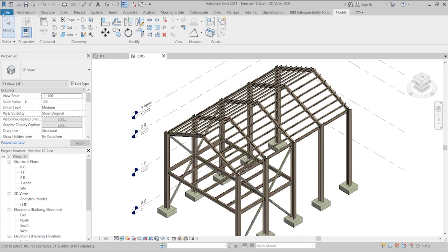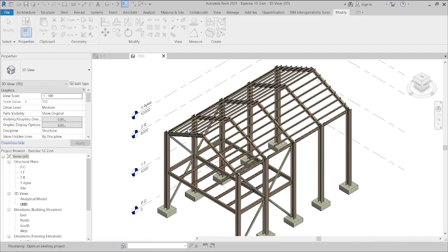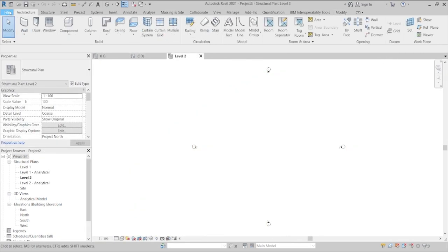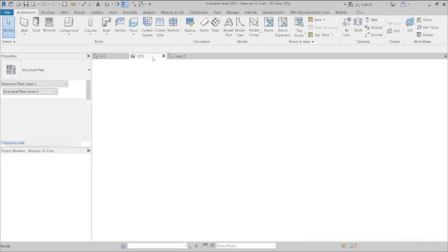To begin, go to File, go to New Project. Choose your template as matrix structural. Click OK, and the template will open. Save your model before you begin. Save as project. So this is where we are.